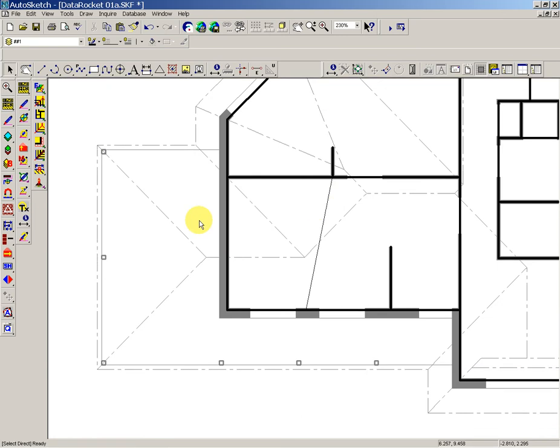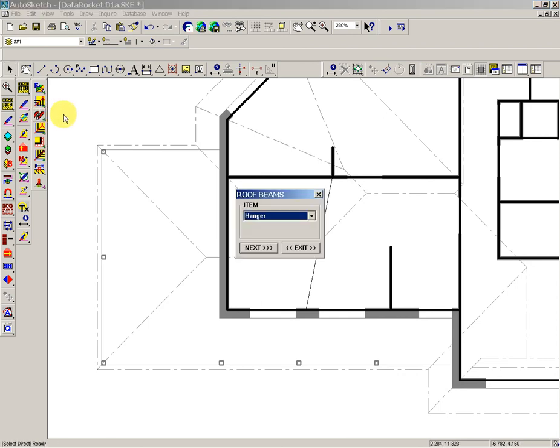So first of all, before we actually put some beams on the drawing, let's have a look at the beam command. Third row down, first item, beam. At the moment it's set to hanger. If I go B for goes to barge, roll the wheel on the mouse, comes down to beam. So you need to set these up for all different types of beams, steel beams, LVLs, straight timber beams. It's your choice, but a bit of thought does need to go into this.